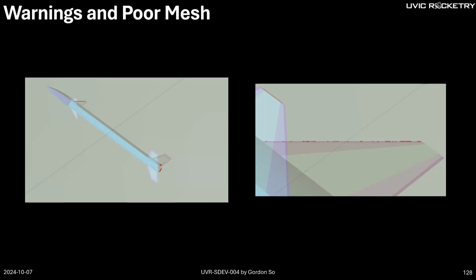And then you may ask, if the mesh is not small enough, we can just make it way smaller, right? Yes, kind of, but that also means your mesh will be really, really small for your boundary layer and your volume mesh. You end up with a really fine mesh, which is too fine. So it's really a balance.